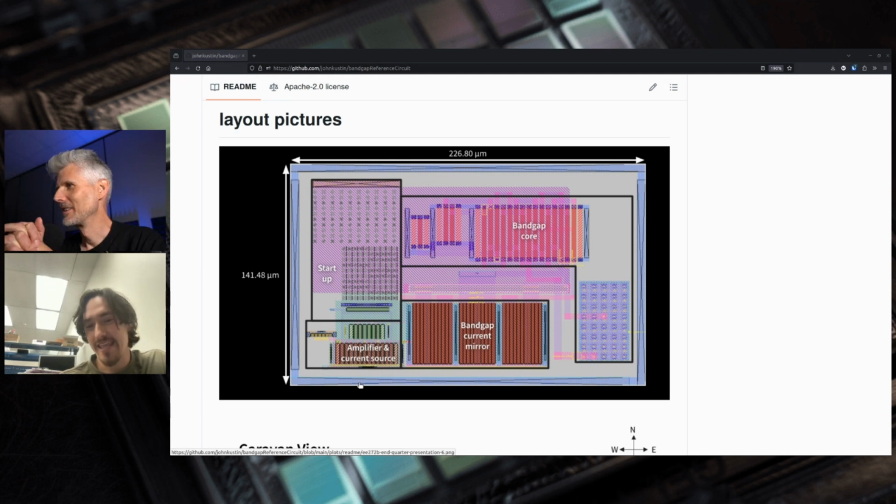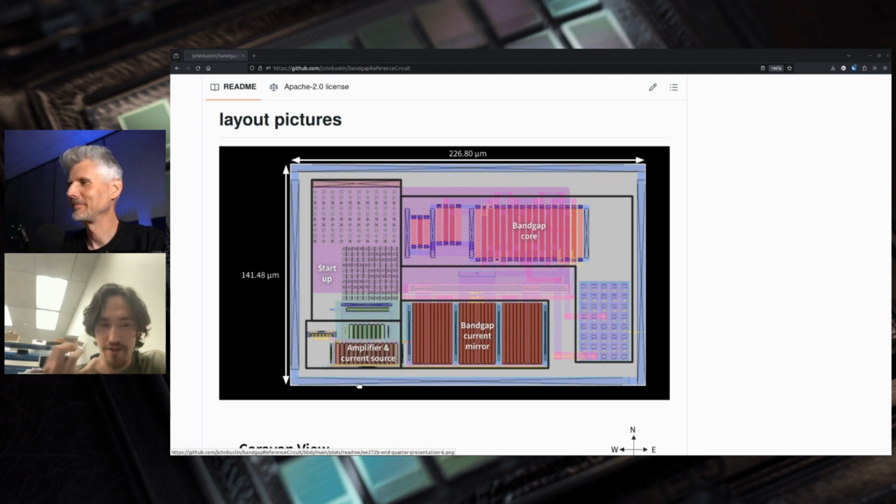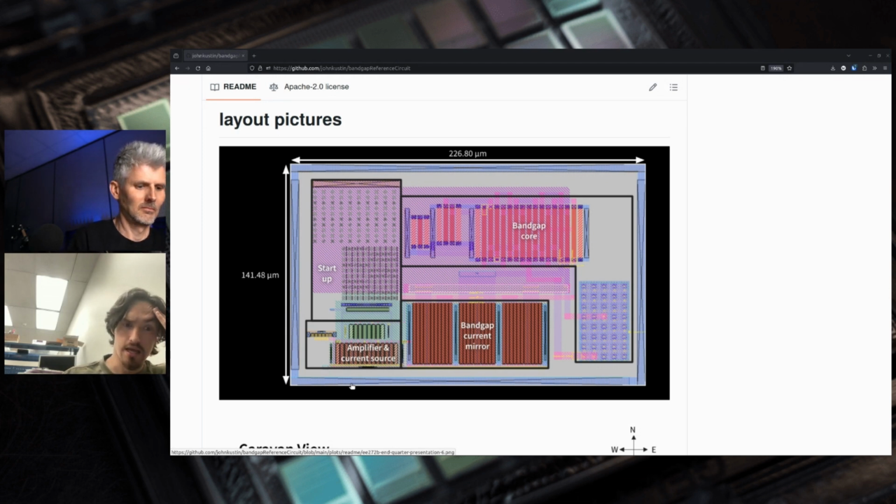But as a beginner, the thing that I held closely to my heart was I need to keep all devices close to each other. And so that's why you don't see the BJTs spread out over area. They're all collected. But if I had to redo this, I would start all the way back from floor planning. And what I mean by that is from a high level, just like a PowerPoint diagram, where does the bandgap core go relative to the current mirror and the amplifier? Because as I did this with no real foresight, I ended up having these very messy wires that go both in vertical and horizontal directions, maybe on the same layer. And that is not standard practice, and ended up leading to, in my opinion, a messy layout.